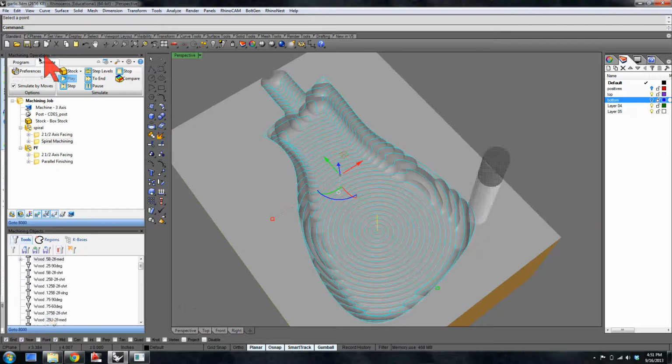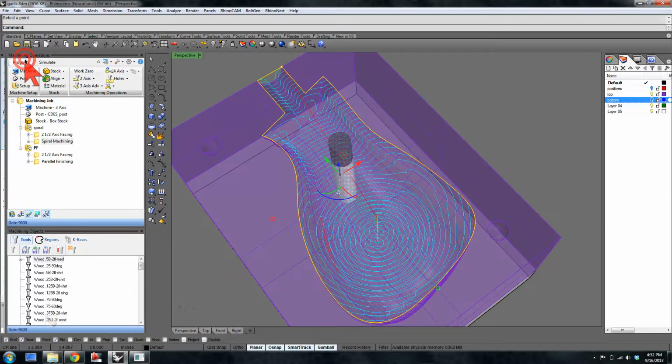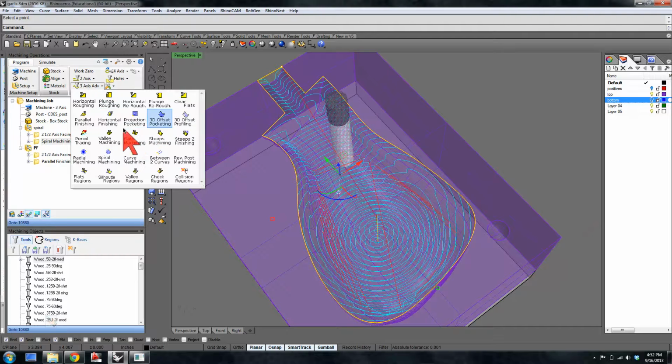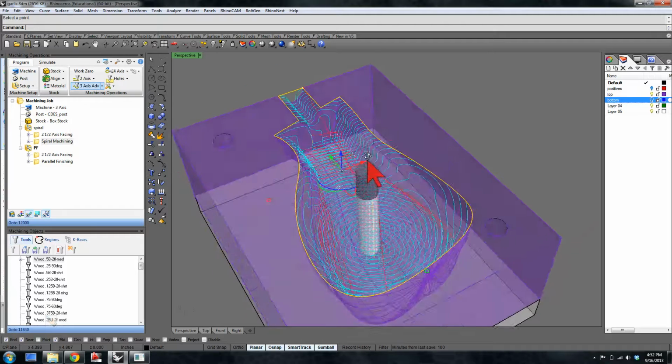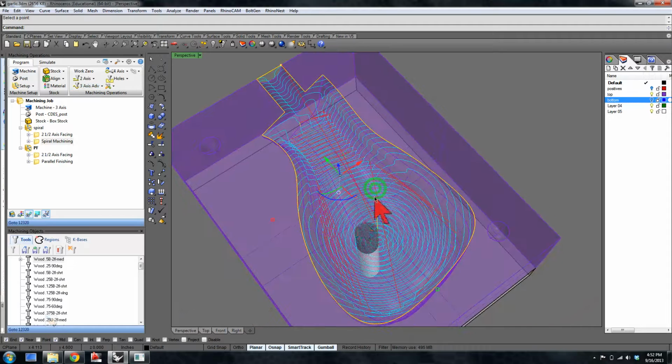And I think basically at this point you guys have a sense of what it is to program 3-axis toolpaths for these molds, and you can start playing with these other ones and see what the output looks like. Basically the machine is going to produce what this preview looks like. So as long as the preview looks right, you should be ready to machine, and come on down and we'll show you how to use the post processor to create your toolpath.